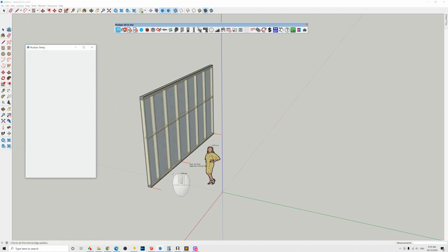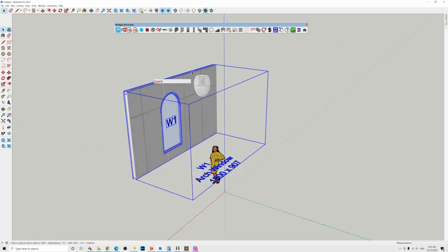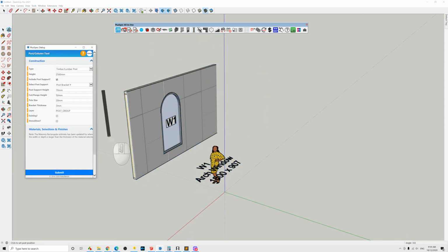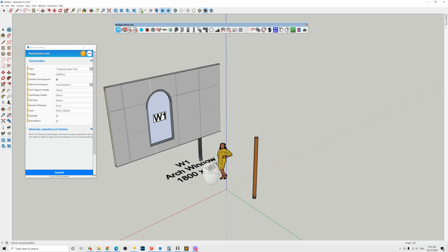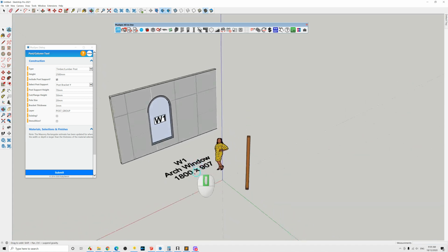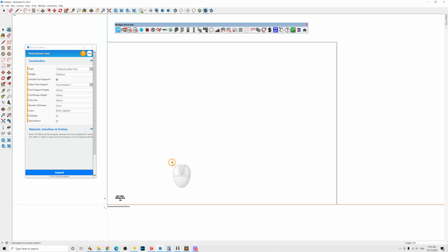And all of this happens really, really quickly and efficiently, and it's going to do a lot of work for you. Right. Doors would be the same as windows. Columns or posts, depending on where you live and what you call them, you can add in a post and column, and you'll be basically tracing over top of a set of plans. Notice I'm in a 3D view. It kind of makes it harder to place things. So if I went back to a 2D view and I place things, they're all going to be on the ground level.